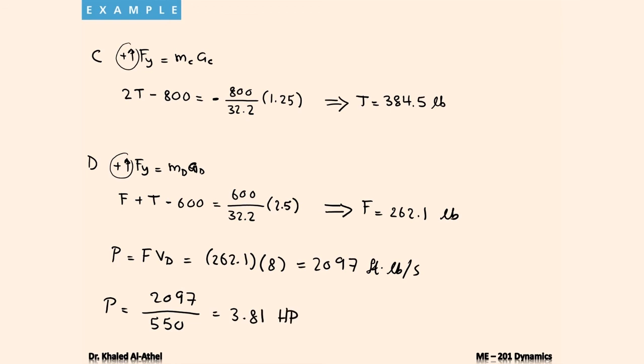And that's it. So the important thing to notice in this module, in this topic, is that these problems with power and energy can be solved using Newton's second law or by using work and energy equations. The point is, once you find the velocity, you just have to plug it into the power equations, and if you are asked to relate input and output, then you have to include efficiency into your calculations.